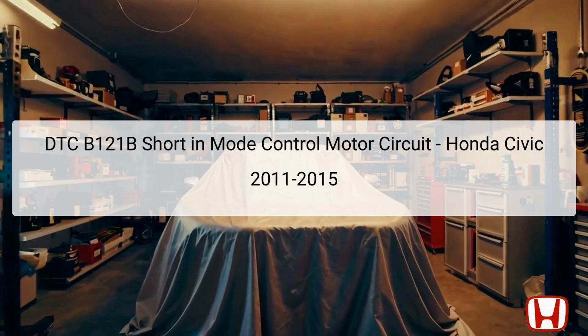This presentation covers the DTC code B121B, which indicates a fault in the mode control motor circuit for Honda Civic models between 2011 and 2015. It is essential to understand that this trouble code signifies a short in the wiring leading to or from the mode control motor. The mode control motor itself is located within the vehicle's climate control system.